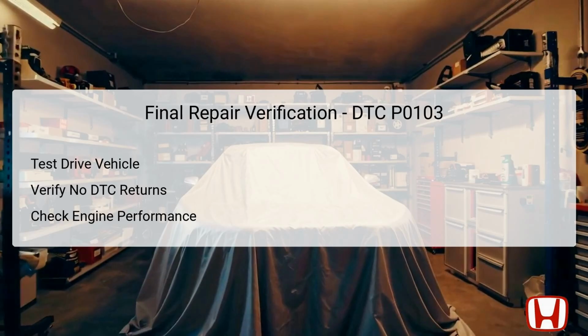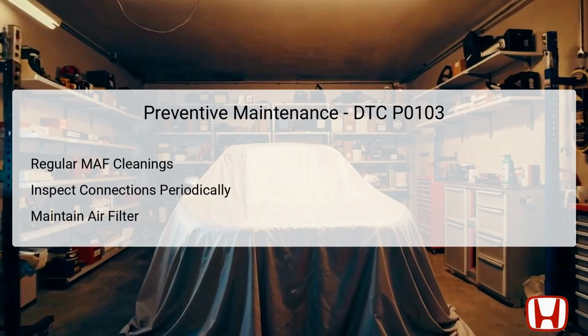Preventive maintenance plays a crucial role in mitigating future occurrences of DTC P0103 related issues. Regular cleaning of the MAF sensor using appropriate sensor-safe cleaners can help maintain optimal functionality and prevent buildup of contaminants that might interfere with accurate readings.